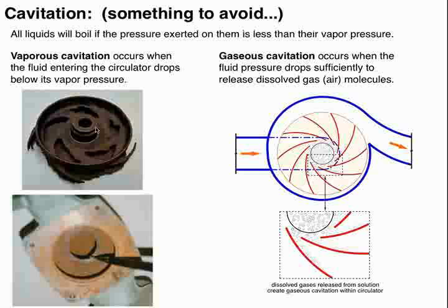I was once reading about cavitation, and it suggested that as these vapor pockets implode, as they collapse on themselves, they can actually accelerate tiny amounts of water to 2 times the speed of sound. So imagine a tiny little amount of water hitting a metal surface at 2 times the speed of sound. That's going to cause erosion. And you can see the results here in this impeller as well as in the volute here.